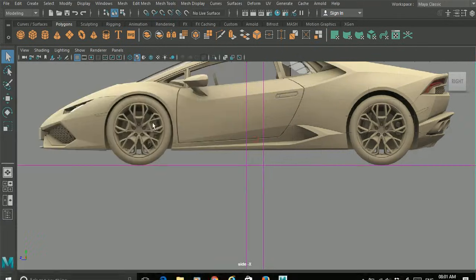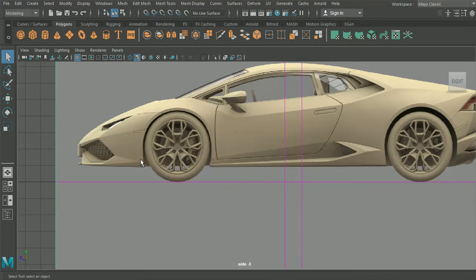circular here. The problem with this, if we were to start anywhere else, is we would have to make this circular shape. So what we would do here is start with a tube, and we would model around this area, and then essentially extrude out from there all the way along the different angles.